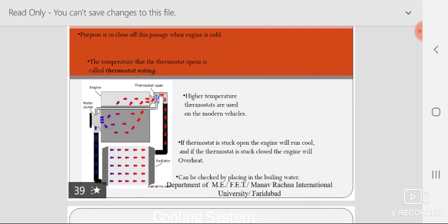Now, the efficiency nowadays is defined as an overall efficiency. It is not only the power at the wheel. It is power at the wheel, power at the compressor of the cooling system, power at the fan of the radiator, power at the water pump of the radiator. There are so many things to be taken into account, and then the output is calculated.